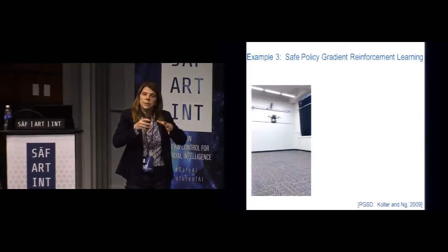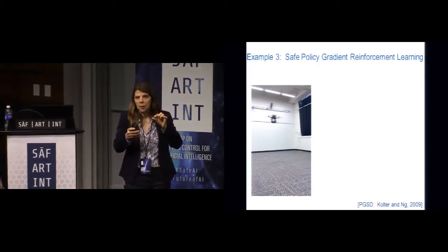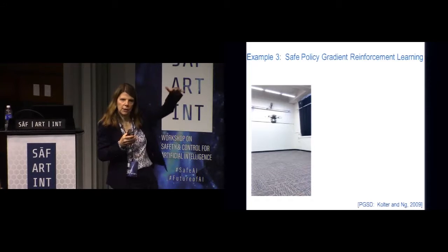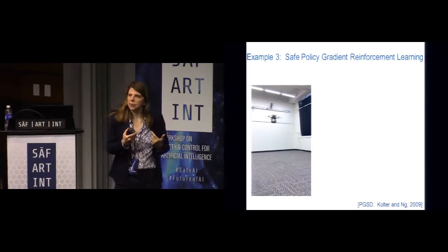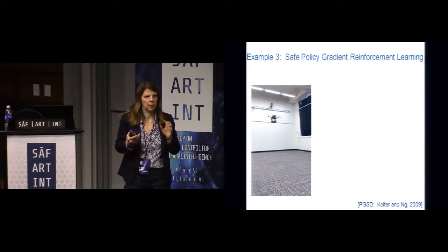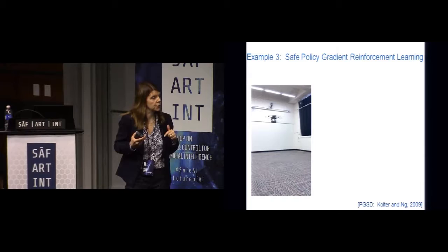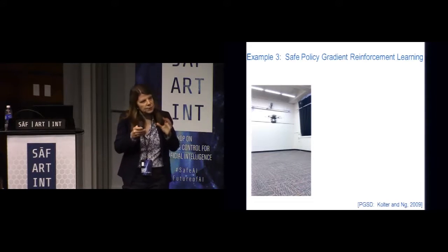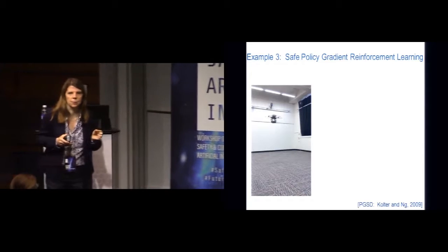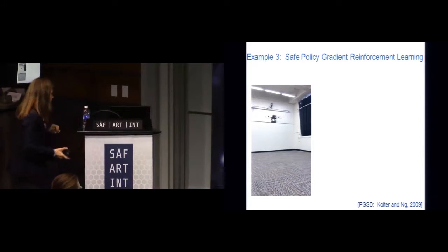The first thing we did, though, was we computed, using the model, the safe envelope. We didn't want it to crash into the floor, crash into the ceiling, so we used reachability, computed the safe envelope, and then we took the model away, and we asked it to learn to track this trajectory inside the safe envelope. So it's somewhat of a contrived example because we used the model to compute the reachable set, and then we took the model away.